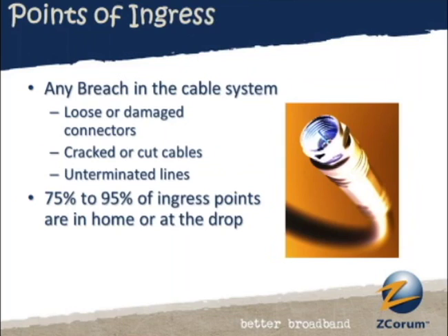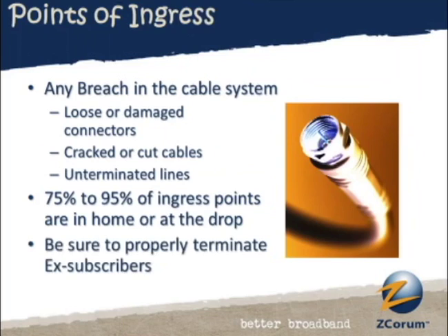It's also cabling that the consumer themselves has messed with, and possibly installed part of, and added splitters and amplifiers and all kinds of things. And even if they haven't physically added things, they move TVs around and they move furniture around. And so especially loose connectors get banged up, they get pulled and tugged on, and that's why we have so many sources of potential ingress. But we also have lots of noisy things in the home to take advantage of those holes. And a lot of people don't realize that they turn that cable a few times, it feels like it's tight, and it's tight enough, right? Right. Yeah. So they don't think about having to be really tight to keep noise out.